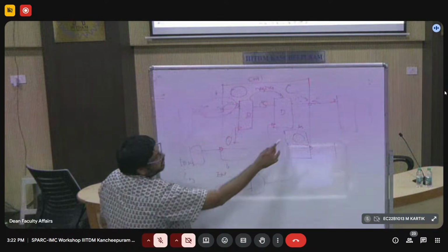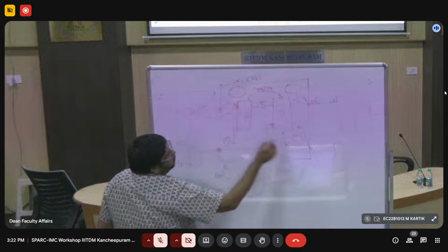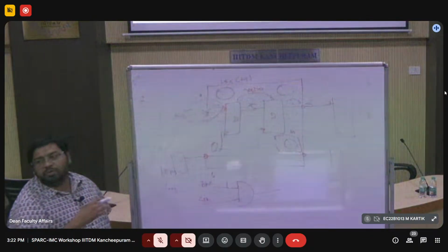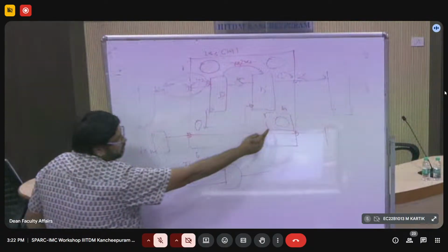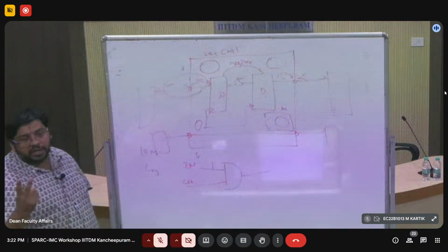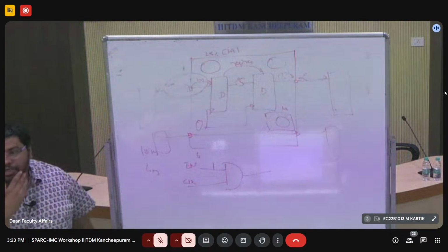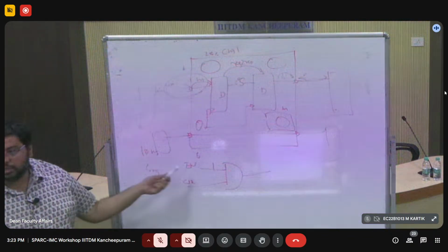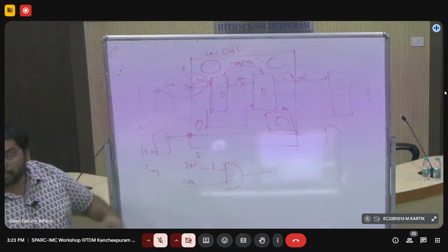So when I do this, let's say all 4 modules have 25% of the components in them. So when I do the clock gating for this module, I'm going to save 25% of the power, right? So that is straight away saved. But what is the issue you see here? Anybody can guess what the issue is? What will probably happen if I use an AND gate?